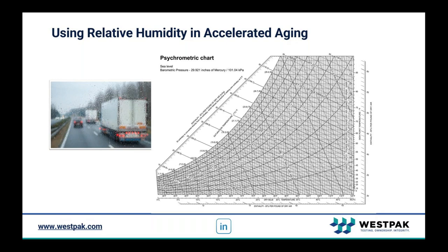That's the same kind of theory with the accelerated aging. If you don't know the characteristics of the materials you're working with, go conservative, go longer durations, go lower temperatures, go lower real-time aging temperatures. That way you have the most conservative approach you can.